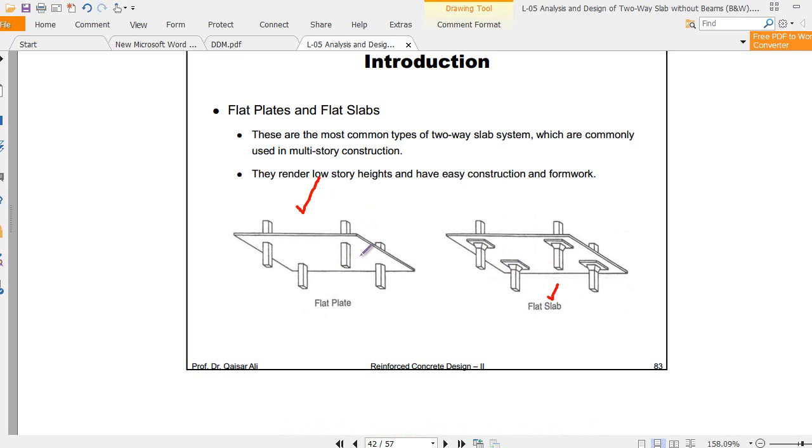Here this is a kind of external technique, used when we are not able to control the punching shear because it is very huge, very large, and it cannot be controlled by column capitals and drop panels, or by integral beams, shear studs and shear heads. What they are, inshallah, I will explain those techniques. So then we provide this kind of external technique. And here you see we have to control the punching shear by internal techniques.